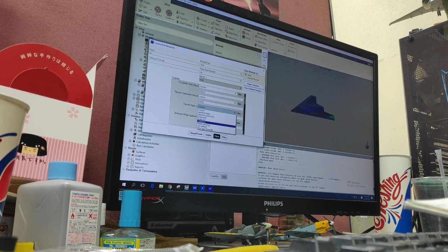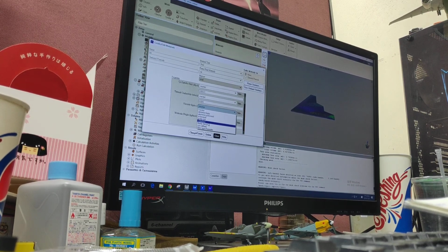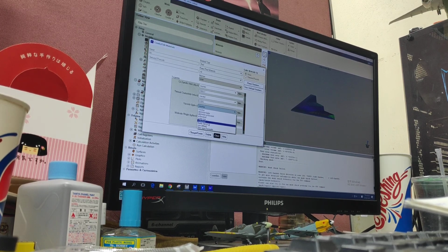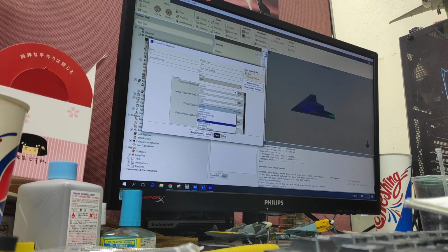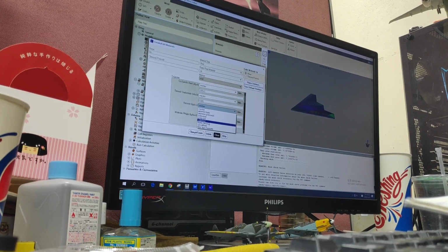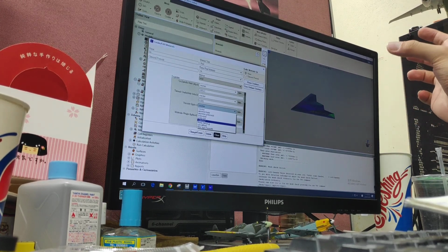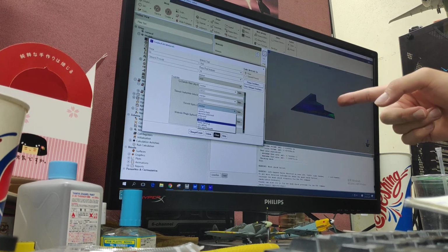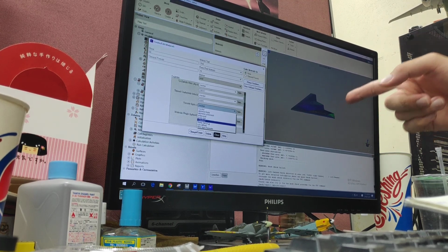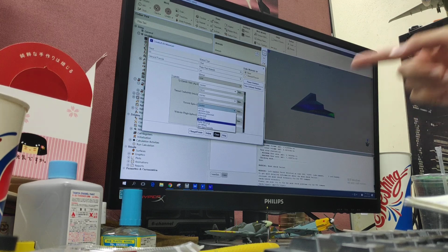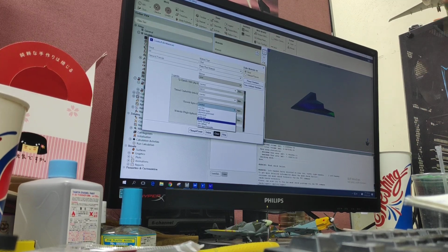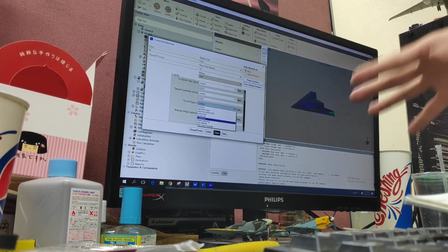But if you're using the other one in water, and you're trying this one in air, then the Reynolds number is not going to be the same. I'm talking about the Reynolds number that we use for setting up the mesh. If your model is still this size and you are using air, your speed or total pressure will have to change.